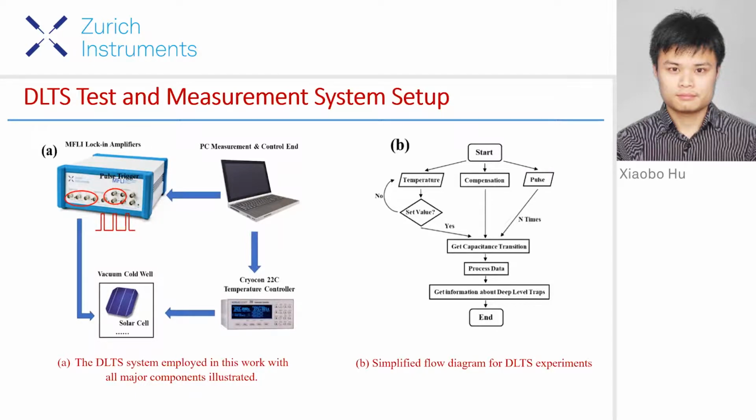The temperature setting, however, is not achieved instantly. It requires a loop control feature to minimize the fluctuation between the desired temperature set point and the current process temperature, and then to improve the accuracy of the process. The system frequency as well as pulse trigger parameters could be conveniently set since the MFLI programming interface for Python is provided.